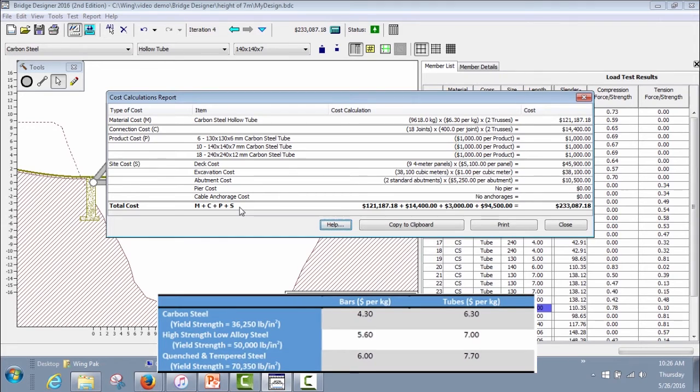In terms of the cost of tube versus bars for the same grade of steel, tubes are more expensive than bars. This is because to fabricate tubes, steel manufacturers need to make steel plates. These are usually bent into the shape of a steel tube. Then along the seam, a continuous bead of weld is provided to close off the tube. There's just a lot more work involved to fabricate a tube versus a solid steel bar. Thus, you have the higher cost between these two items.